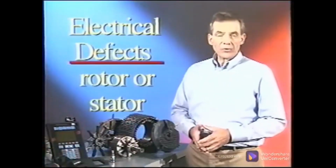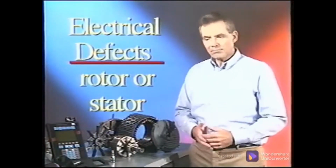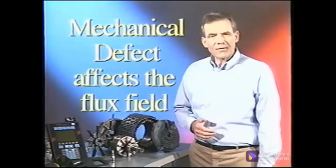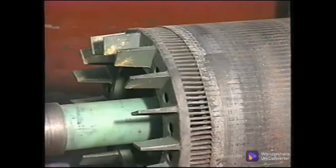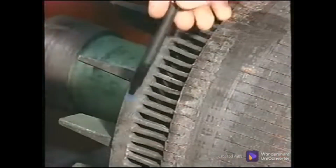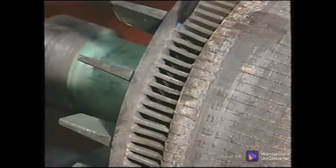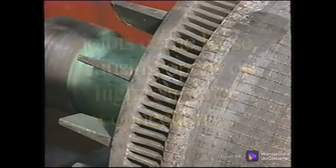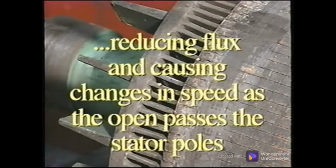Electrical defects in motors are either in the rotor or stator, and are most commonly a mechanical defect that adversely affects the electromagnetic field or flux. In a fabricated rotor, the most common problems are at the joints where the rotor bars join the end rings. These joints may become loose, causing opens or high-resistance connections, which restrict the current flow, causing the flux to be less for that rotor bar.